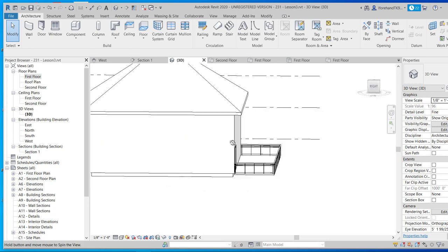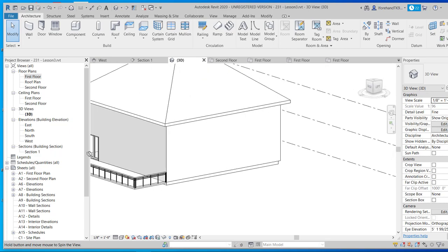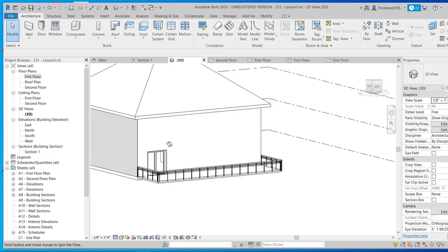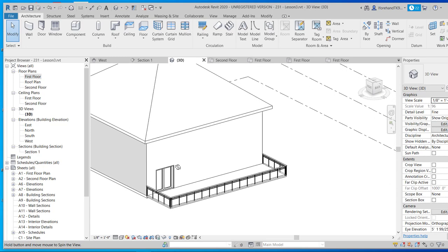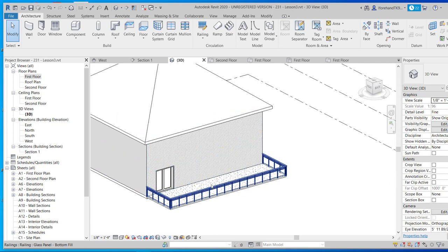Superb. So what we do not have is a roof. And it's hot. We want to make sure this is a shaded area. We are going to need to just have a roof over this area. So one way to do that would be to create a specific kind of roof that's called an extruded roof. An extruded roof allows you to draw a profile, and then it will use a type of roof and extend it almost like an extrusion through. And I will demonstrate what I'm talking about now.